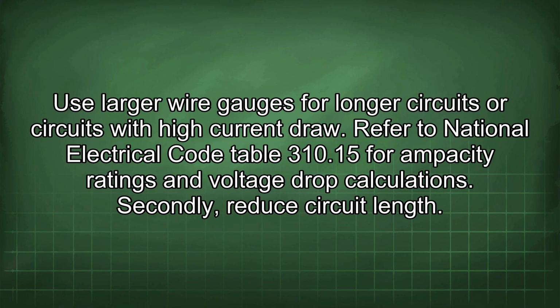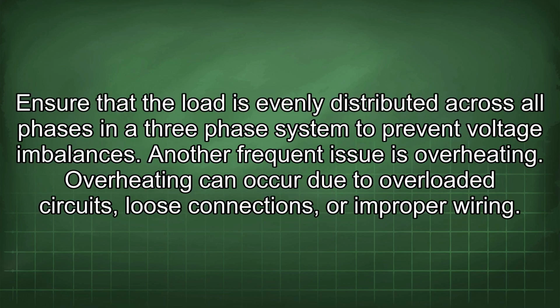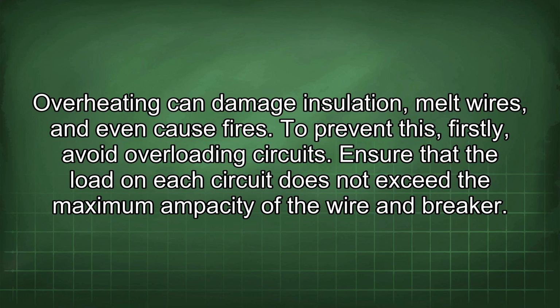Secondly, reduce circuit length. Shorter circuits experience less voltage drop. If possible, divide long circuits into multiple shorter circuits. Thirdly, balance the load. Ensure that the load is evenly distributed across all phases in a three-phase system to prevent voltage imbalances. Another frequent issue is overheating. Overheating can occur due to overloaded circuits, loose connections, or improper wiring. Overheating can damage insulation, melt wires, and even cause fires.